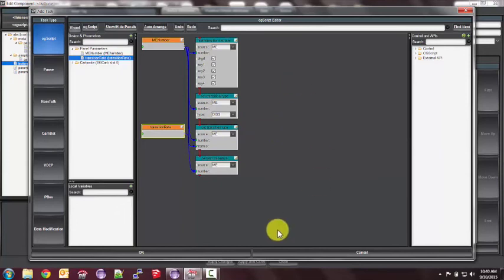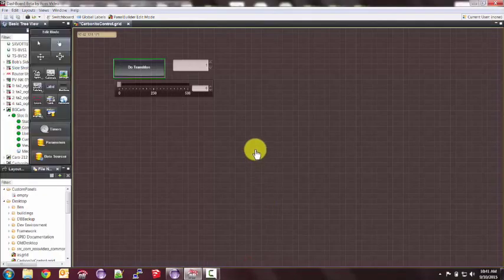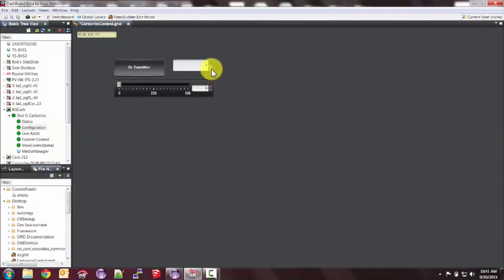And that's it. We now have our script that'll set what occurs during the transition, what type of transition is occurring. It'll set the rate to wherever we specified on the panel, and then perform the transition, all on the ME number that we specified in our panel. So if I hit OK, Apply and Close, Control-G. Now, if I want my transition to occur on ME3, and I want it to take 125 frames, and now if I hit Do Transition, my Carbonite is now transitioning on ME3, and it's taking 125 frames. That's it.